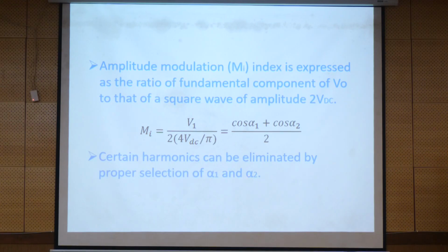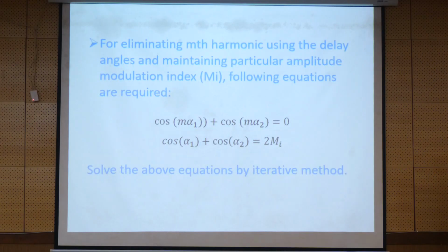I do have the algorithm for this one, but we can eliminate some harmonics to solve it, using the Newton-Raphson method, an iterative method. And one more thing: for eliminating the harmonics using the delay angles, we have to maintain a particular amplitude modulation. The amplitude modulation is also important: how much do you want, and what is the range of amplitude modulation?